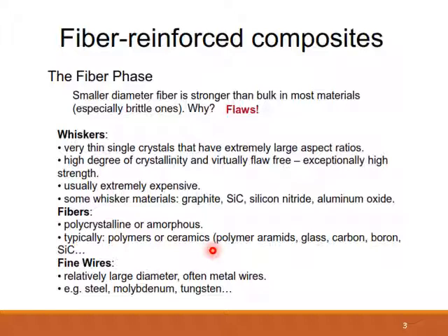So let me give you a typical example of where steel is used as a fiber. In reinforced concrete, you see the metal that is used in reinforcing concrete. If you want to design a building, you need to make concrete, and the concrete is usually reinforced, because concrete is going to give you a very brittle structure. The brittle nature comes with its high strength. So even though it has high strength, because it is brittle, anytime a crack sets in, the crack will propagate easily. So in order to toughen that concrete, you reinforce with a ductile phase. That ductile phase is usually steel. That is why on a construction site you see steel used to reinforce concrete. So you see that the steel there is playing the role of a fiber reinforcement in the concrete matrix. This is a typical example of where you have steel as a fiber in reinforcement.